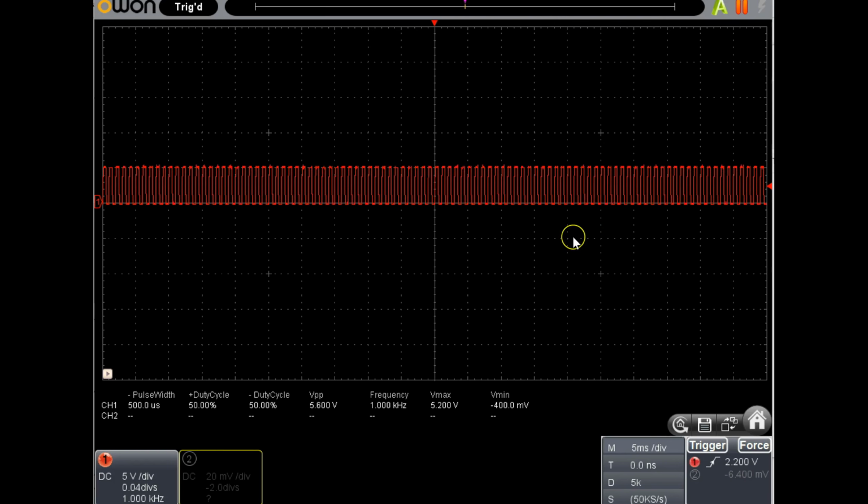So that would be 20480 Hertz. Right, so that will be the sampling frequency. The Nyquist frequency is half of that. And so we're going to see a display that will put frequency from 0 out to the Nyquist frequency based on this particular time base value.